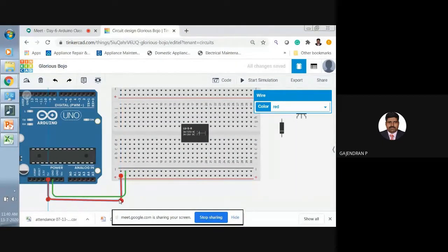Meantime, if possible, draw the circuit diagram once, then only can you become familiar with the circuit easily. Okay, now, so these two are coil terminals. Terminal number 5 and 8. So terminal number 5 and 8 are coil terminals.